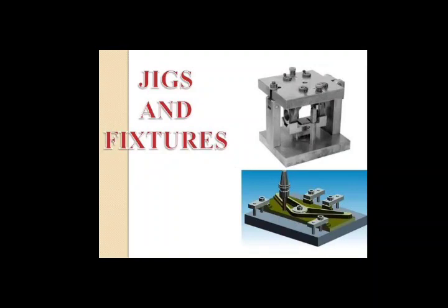Let's go ahead. What is the need of jigs and fixtures? While carrying out any machining operation, it is required to hold the workpiece securely onto the work table. You agree with that? So that the workpiece will remain in its position and it can go through the machining operations. In operations like turning, boring, tapping, reaming, etc., it is required to guide the tool if there is mass production. This provision will reduce overall machining time.